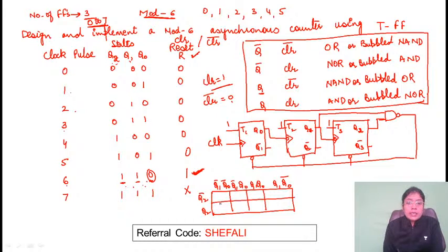We just got the expression, this is 1 and this is 0. So it's going to form a pair. And what is the equation for R? For R, when will it reset? When it is Q2, it's connected with Q2 and Q1. So one of the inputs is Q2 and the other input is Q1. Right? So you just have to determine the value where it has to reset, and on the basis of that get the minimized expression and implement this.